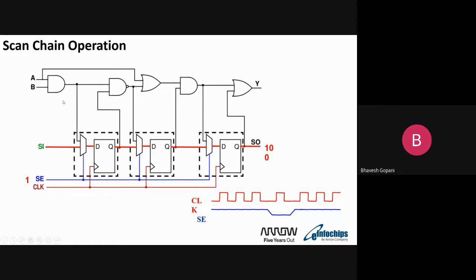In a real scenario, the gate works at at-speed frequency. In the real environment, in functional verification with functional vectors, data is continuously changing and the clock is at-speed, so at-speed transitions happen in functional mode. So to make sure this gate has no issue, transition testing is a must.